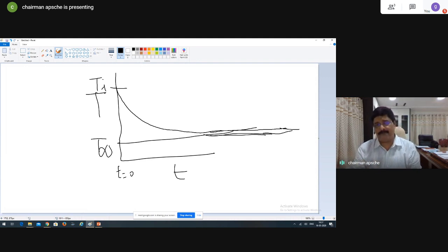With a constant fluid temperature, it's fine, like measuring your body temperature or measuring water temperature in a glass, which is not varying much. Whereas measuring the temperature of an engine cylinder, in the suction stroke, right from TDC to BDC, it is changing. And again in the compression stroke from BDC to TDC, it is changing. Because it is compressing, it is heating up, and all of a sudden you are burning the fuel, be it CI or SI, and enormous heat is released. Temperature surges very drastically, pressure is increased, and it pushes the piston down. So in every stroke the temperature is varying.